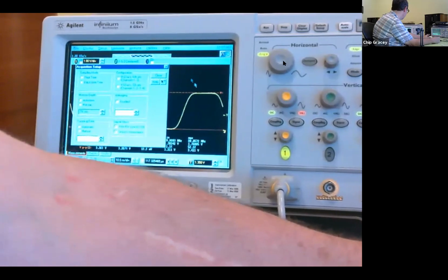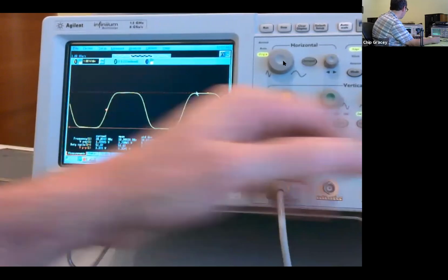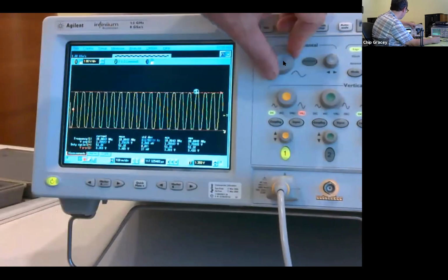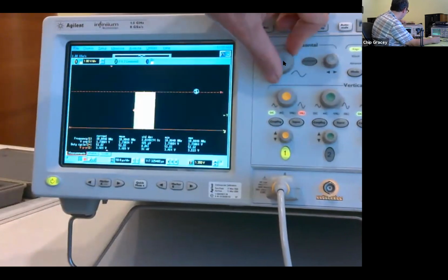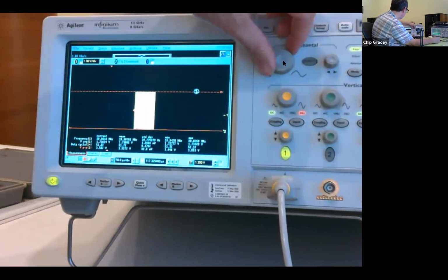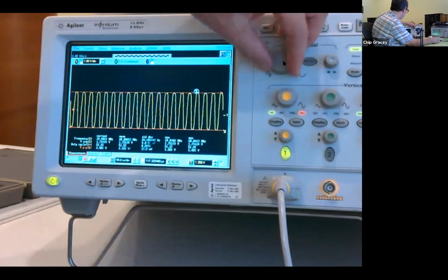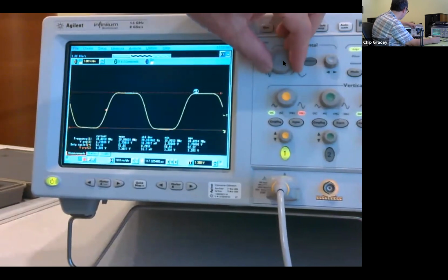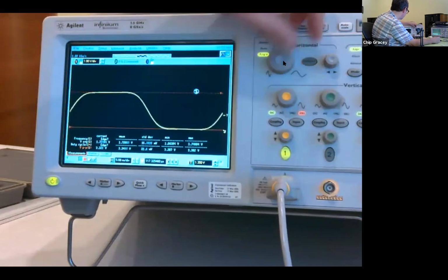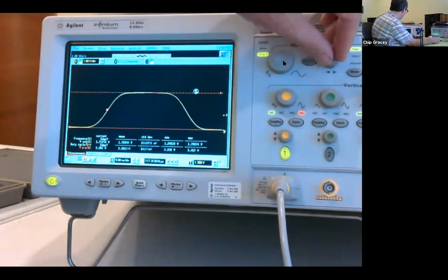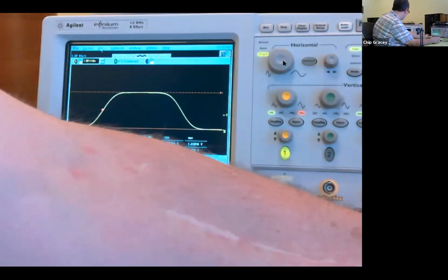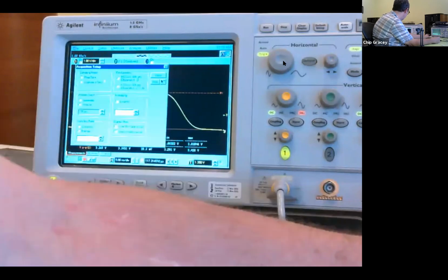You see this down here? We're 117 microseconds out, so I set the trigger. You've got to zoom way out, and the trigger is all the way over here. I did that to show that there's no long-term jitter, or very little anyway. Here's 2 nanoseconds, here's 5 per division. And if we really care about just looking at where the edge is, I can go back to 8.